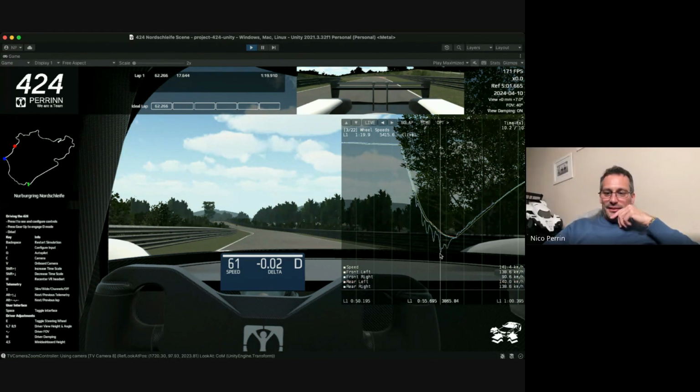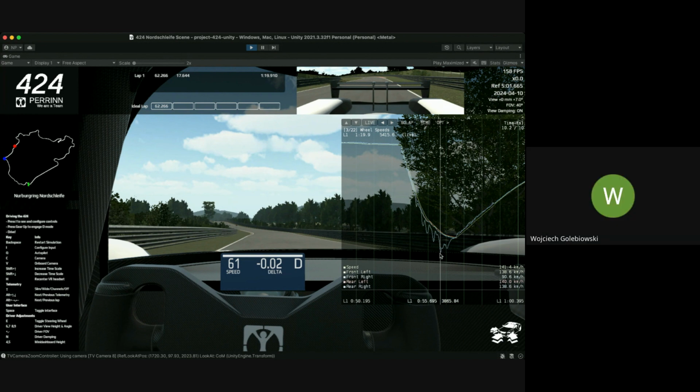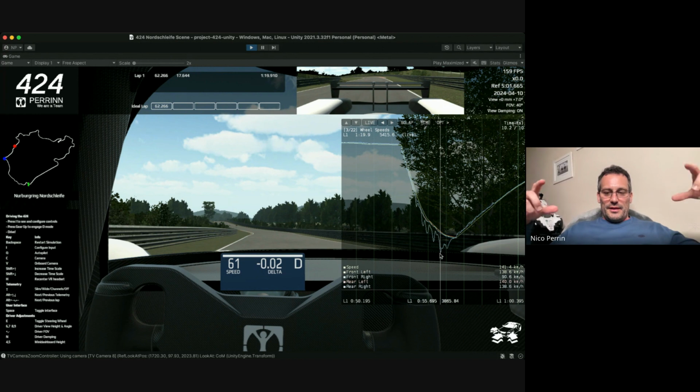Okay. So here, effectively, everything's in kilometers an hour. What we measure on the car is the rotational speeds, in RPM, for example, rotations per minute. And then we just use the radius of the tire to get a velocity. But you're right, the actual measurement is the rotational speed. We always do that in a race car. It can be a constant number or it can be a variable number with different parameters. It's what we call the rolling radius of the tire.